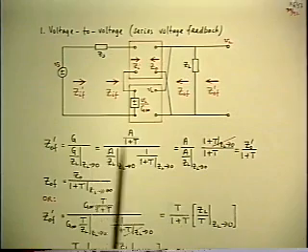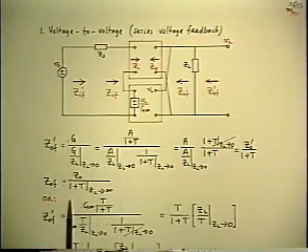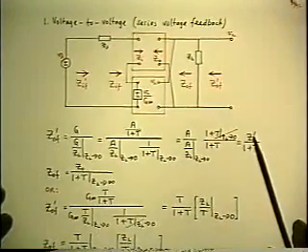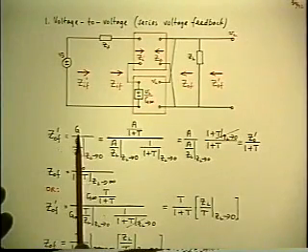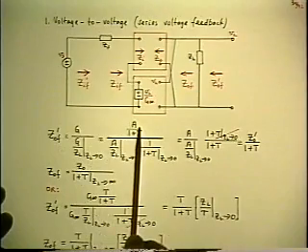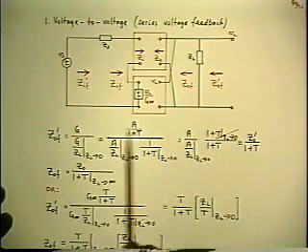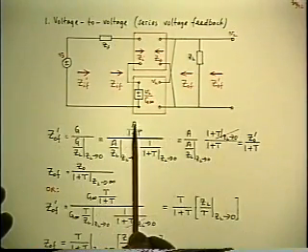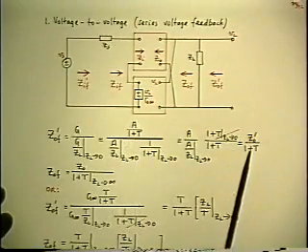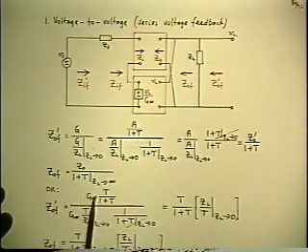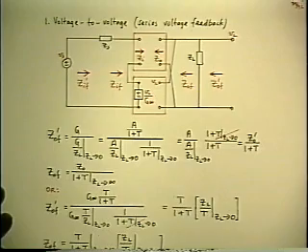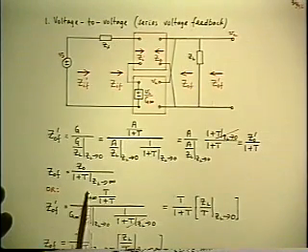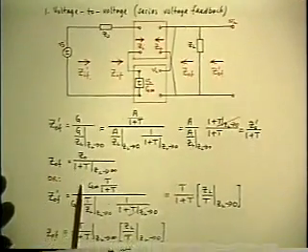And so the trick to do that is, in the very first line, when you want to apply the output impedance theorem, instead of substituting for the closed loop gain G in terms of the open loop gain A, that's where the open loop values got back into it. Now we don't want to do that. So substitute for the G in terms of the new version, G infinity and T, which are the quantities we're interested in. So here's what happens when you make that substitution.